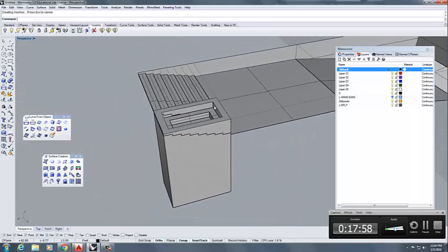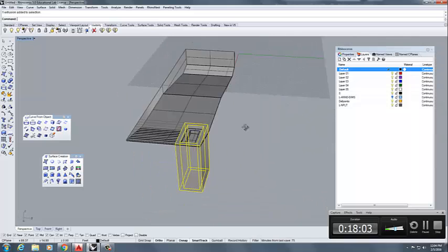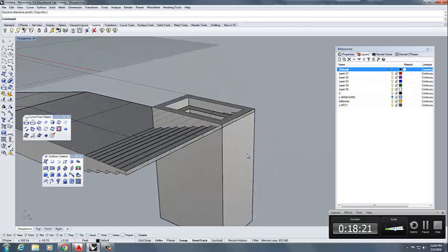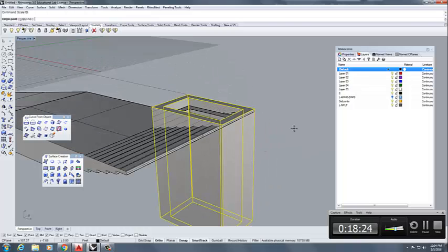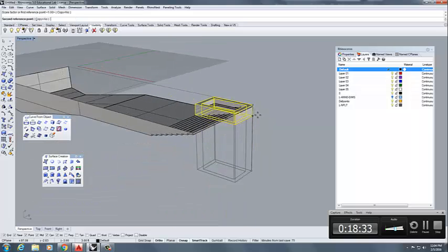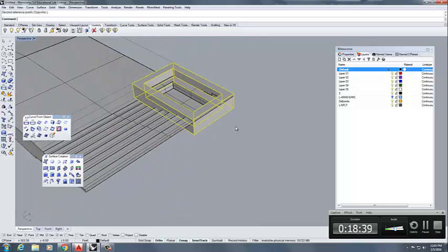Same thing here. This time, I actually want maybe these walls to come up to the depth of this spot. I'm going to use that command that I've mentioned a couple times, the scale 1D. If I was to type scale, and I selected this point, and then this, whatever, it scales it all in 3 dimensions, right? I just wanted to do like a push-pull in SketchUp. So in this case, I'm going to type scale 1D, and it's going to ask me origin point. I want to hold this point. I don't want this point to move. And now a reference point. I go down here, and where do I want it to end? Well, I can snap to that base that I created for the bottom of things. Click. We're good.